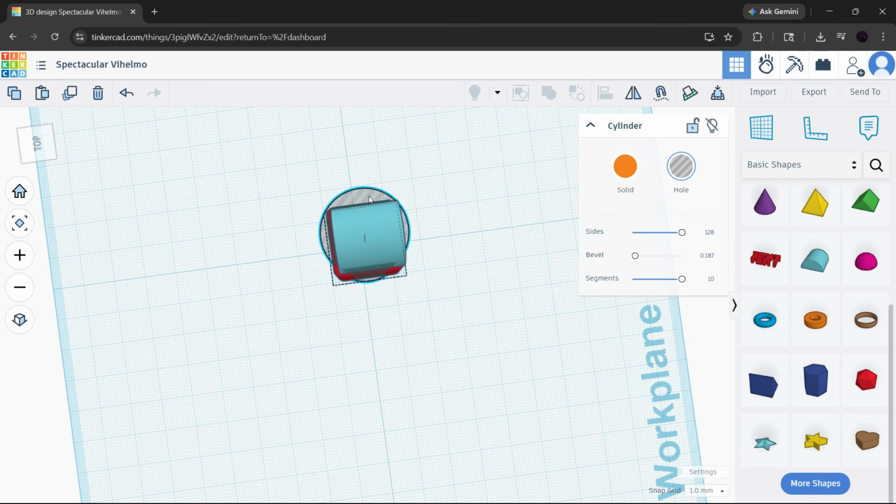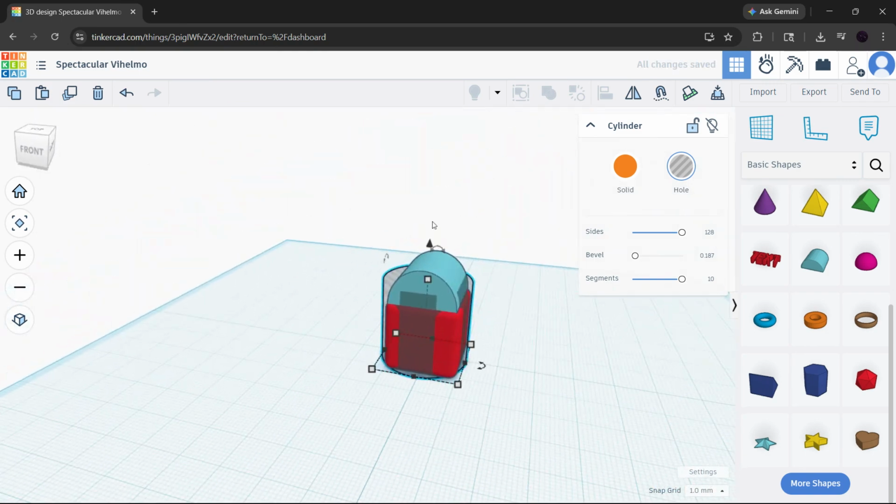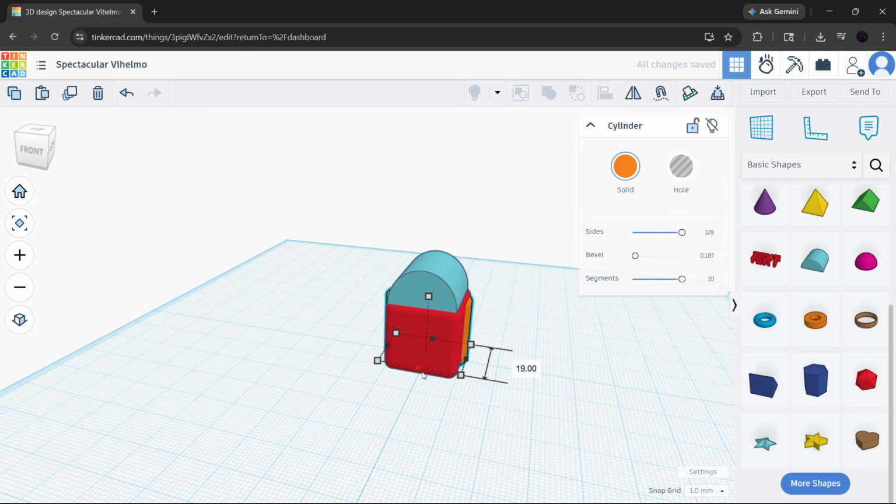Once it looks right, select both objects and group them. Tinkercad will combine the shapes and remove the sharp section, giving you a much smoother edge. If you want an even cleaner result, you can combine these techniques. For example, you can use the radius slider for general rounding, increase steps for smoother curves, and then use a hole cylinder for custom corner cuts. That way, your design looks refined from every angle.